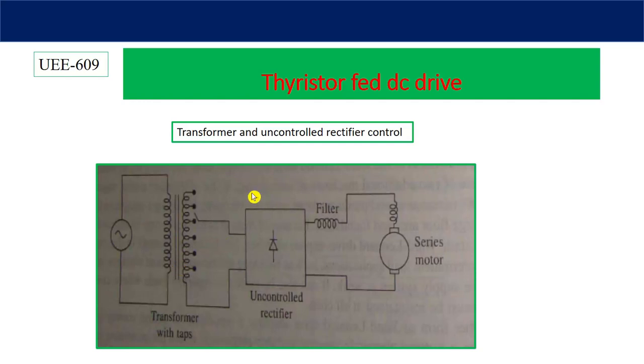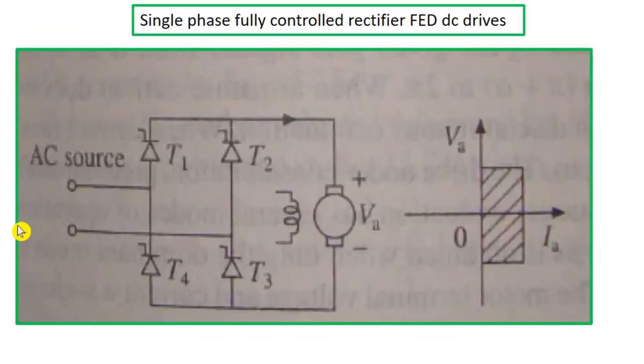Let's see what are the other available options. Here it is, controlled rectifier. Now these are thyristors. In place of thyristor, we can use transistor, MOSFET, IGBT, GTO, and other switches also. For high frequency application, generally MOSFET is preferred, but MOSFET is not suitable for high power applications. For medium power application and medium switching frequency around 20 kHz, IGBT is preferred.